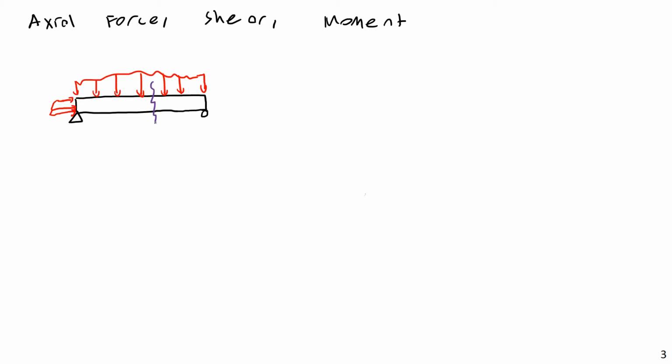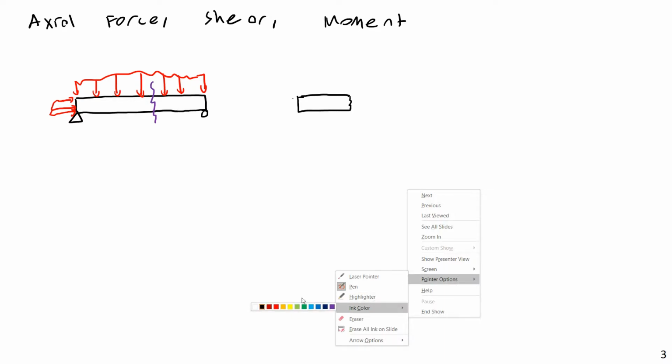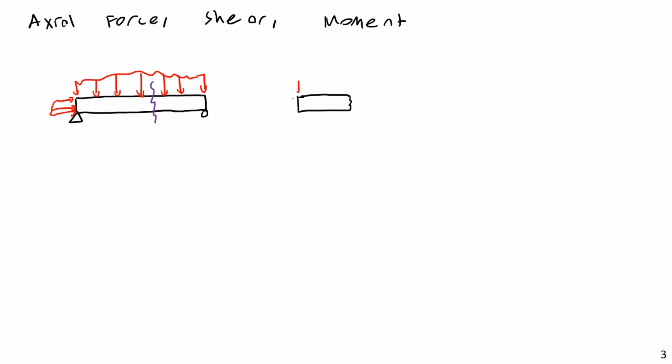Okay. What I'm going to do is cut this beam, and much as we've done previously when we've looked at the method of sections and trusses, I'm going to ask, when I cut this here, what kind of internal forces can exist within the member. So I'm going to cut this, and I would have the same general loading up to the cut and from the side there. I'll just show this as a cut surface. And then let's look at the loads. Whatever general loading was there before to the left of the cut is still going to be there. And same here.